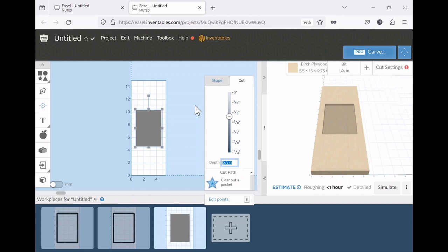And since we have a 3/4 inch board, we're going to take 5/8 of an inch away from it, and that'll leave us the dimension we want. So we're going to change the depth of cut to 0.625. And now we're going to cut out 5/8 worth of material here.